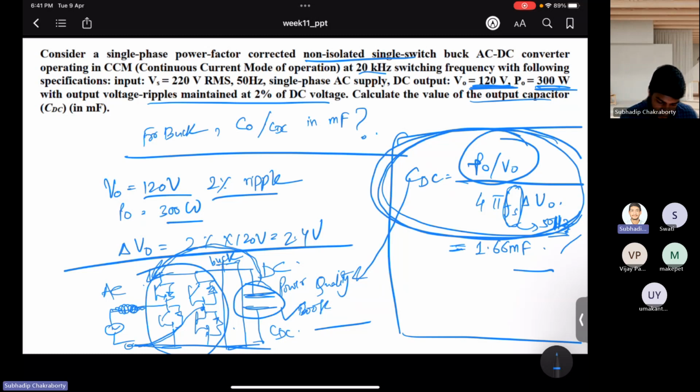So you can have these switches maybe unidirectional, maybe bidirectional. For the input to the buck, you can use this concept, the diode bridge rectifier or whatever the modulation index is. You can calculate the DC link voltage at this point. And if you assume there is a buck, you can calculate for the buck accordingly, as we did for the boost. So specifically, some conditions may be given that for this modulation index you calculate.